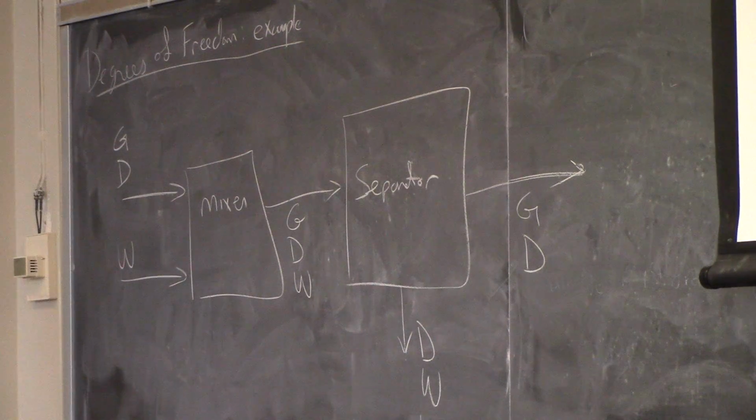Label the flow components. Show any components in each stream and accumulation. Do we have any accumulation in the system? No, so why do we know this is steady state? What kind of process is it? Continuous process, not batch, not semi-batch. So stuff's moving through on a per day basis. This thing is just regularly going.